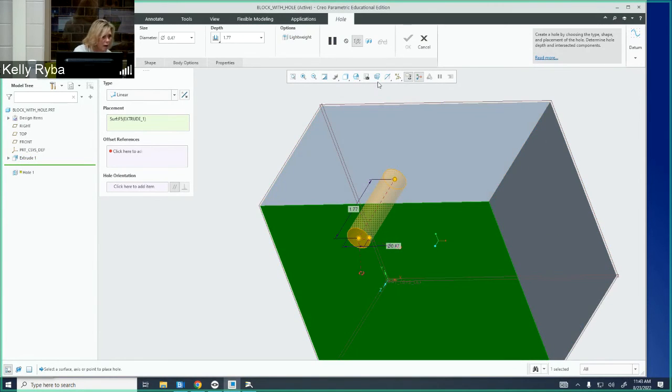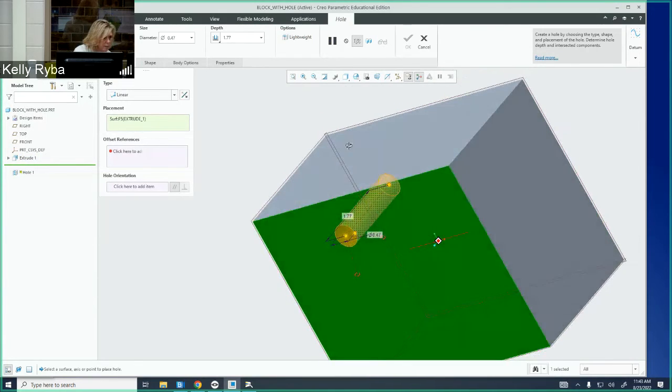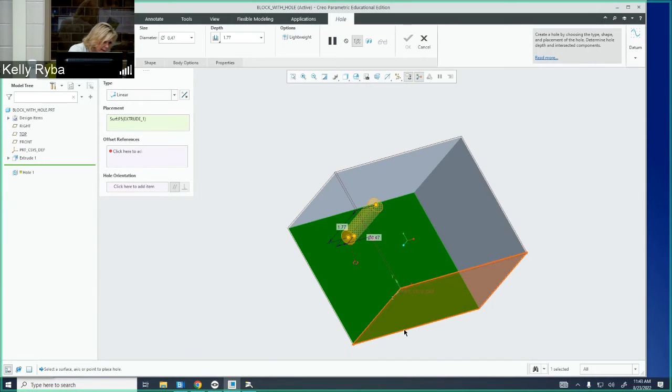All right, now I can reorient myself here. And I'm going to notice a couple things. I now need to dimension it to the sides of the part. So I've got to look on page 11 at the bottom. They want us to place this 1.5 inches from the bottom. Okay, so that would be this edge right here, this surface, and 2.5 inches from this right side over here.